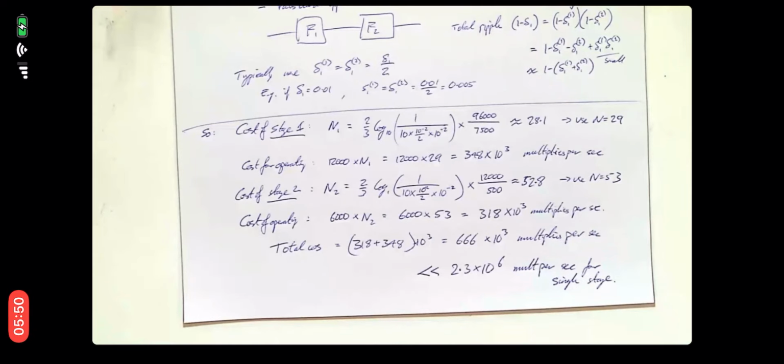Okay, so that's the multi-stage, multi-rate part. It's just showing that if you want to do this process, it's very much worth looking at multiple sections for this. There's some practice at this in the tutorial. It's not always guaranteed that this will work. You might think, oh, maybe we can split it into 3 stages, 4 times 2 times 2, that may actually end up being more expensive because you're just paying more to do that. Doesn't necessarily mean splitting it down as much as possible is going to be the best way of doing it. So you may have to just experiment with things to find out which works and which doesn't work.